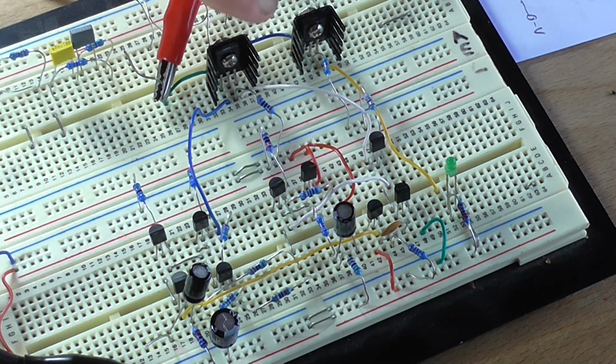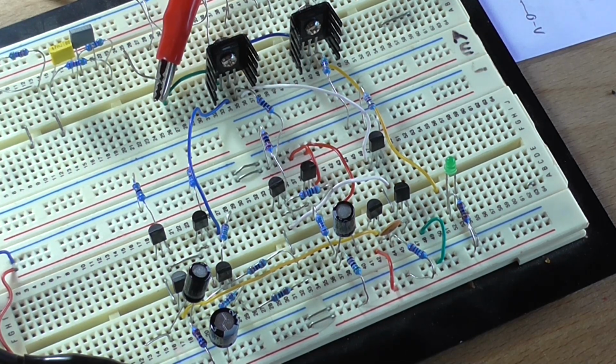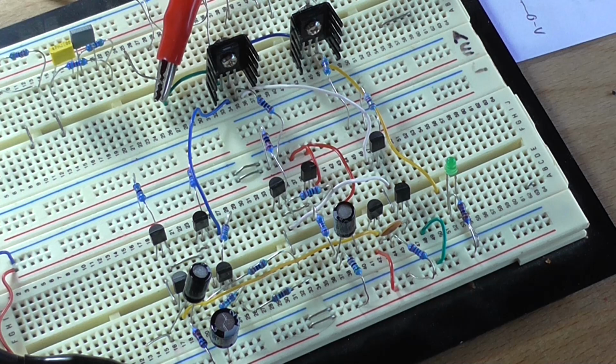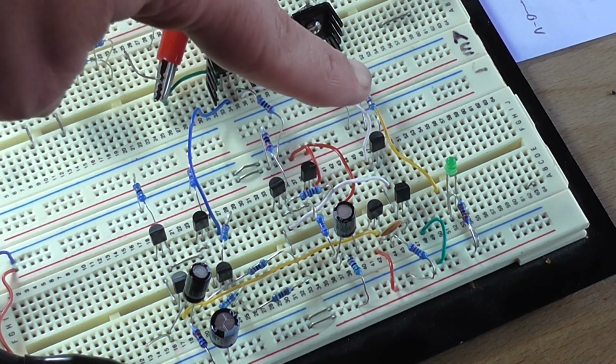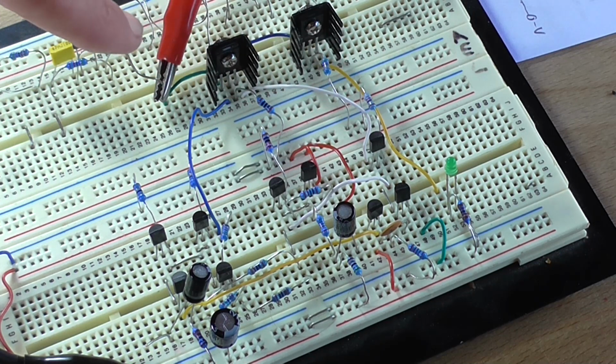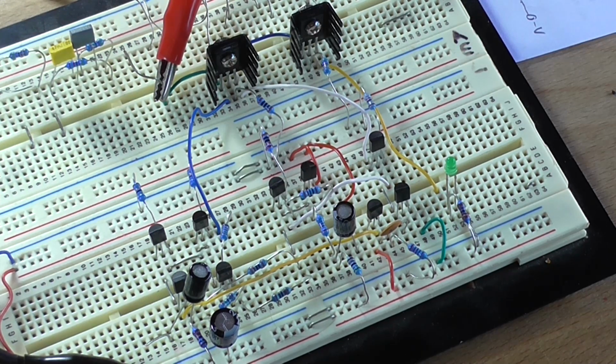Yeah. And up here, this transistor is the output transistor, and this one is the current sink. Now, I'm going to do a preliminary test at plus minus 12 volts. The LED should light according to the instructions, and measure the output voltage on the multimeter. It should be close to 0 or up to around 30 millivolts is acceptable, apparently.